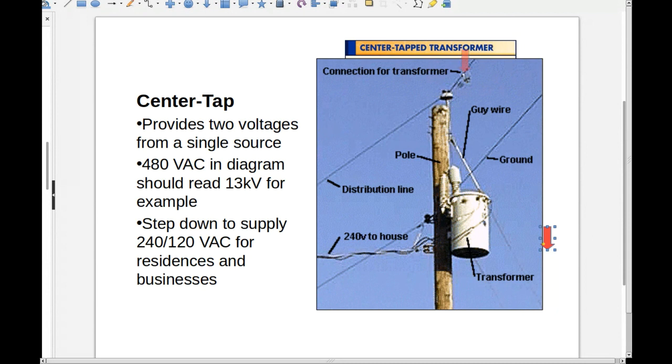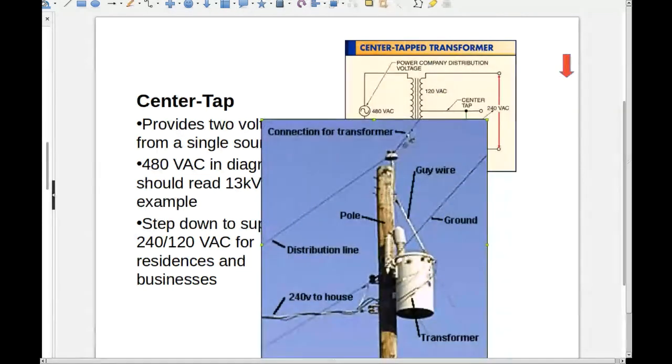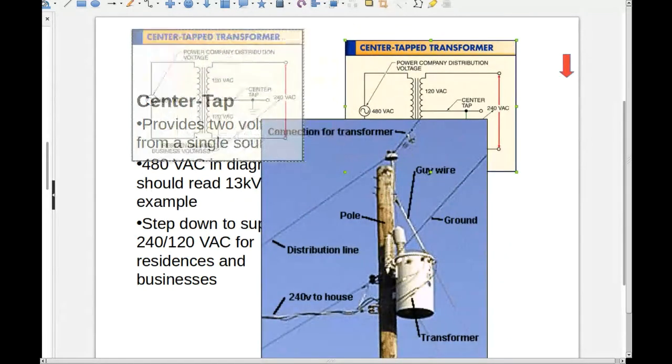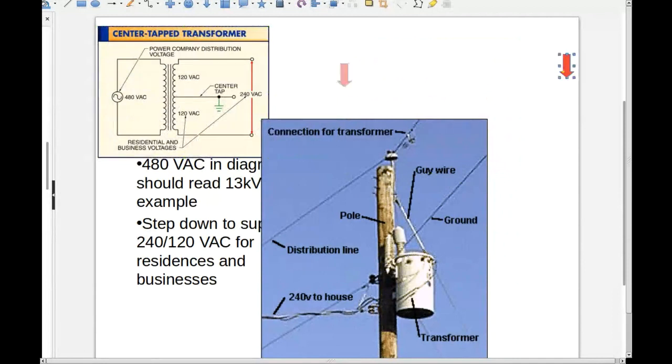Because for them to provide you electricity, they have to have two wires. You've got to have current flow, so you've got to have a complete circuit. So here's this one wire coming in, and then there's the ground wire. Notice this one's high voltage, maybe 10,000 volts, and that's why it's so far away, whereas this one is effectively 0 volts, it's ground.